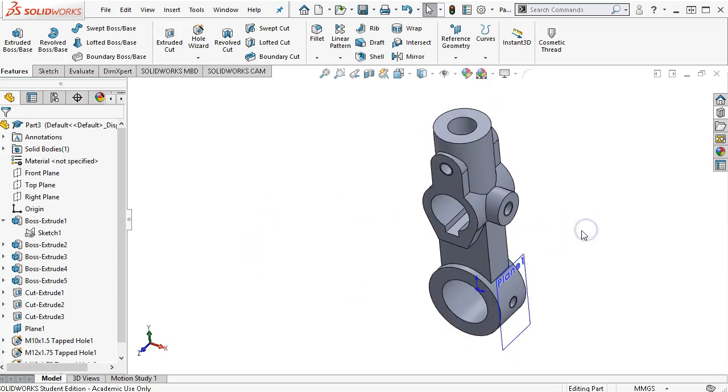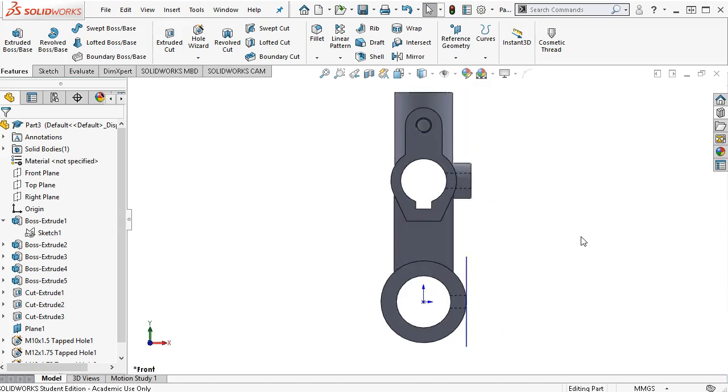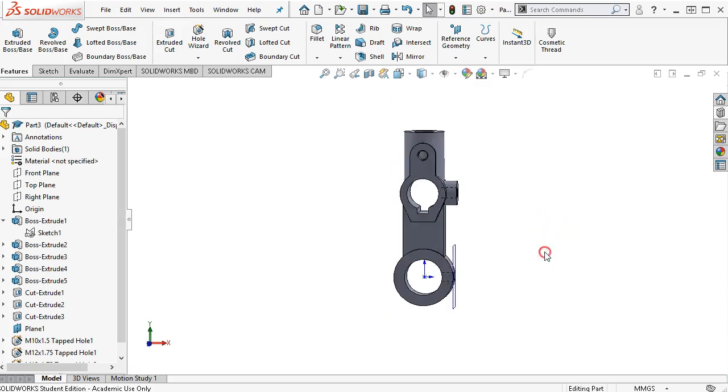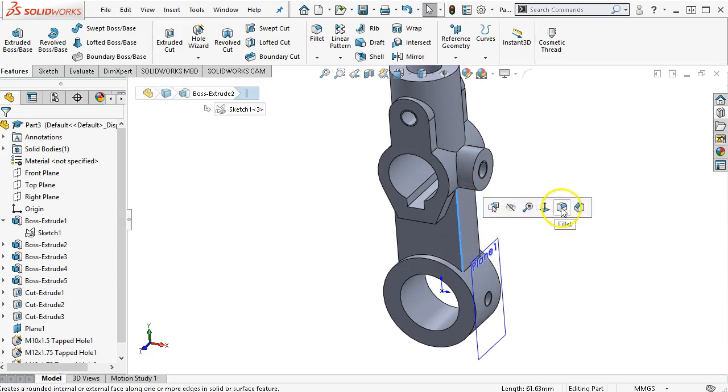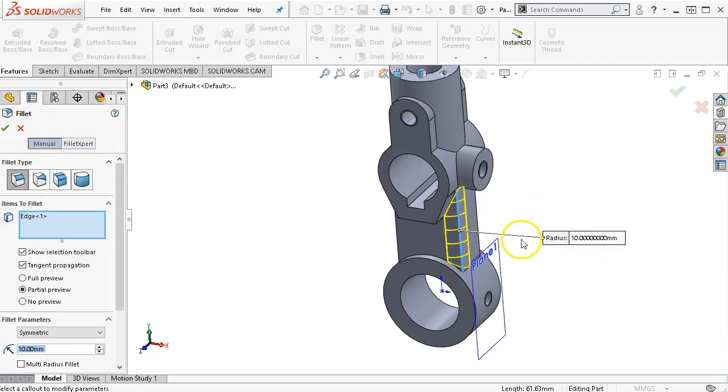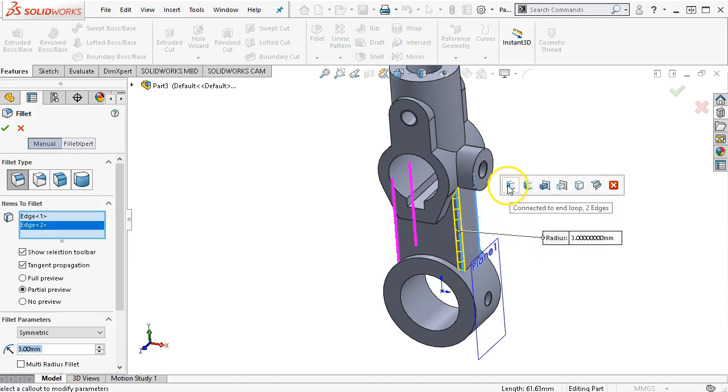All right, so a couple of quick checks. Did we miss anything? Where are our fillets? Fillets and rounds are all radius of 3. I don't see anything called out as different. So that being the case, let's pick one, get it started, and see if we can get the rest of that geometry going in some pretty decent shots.